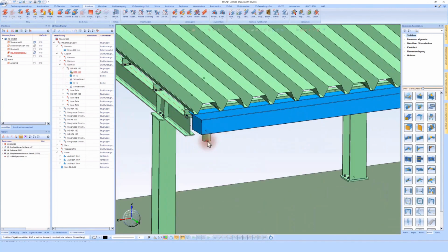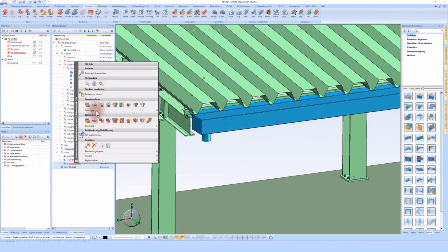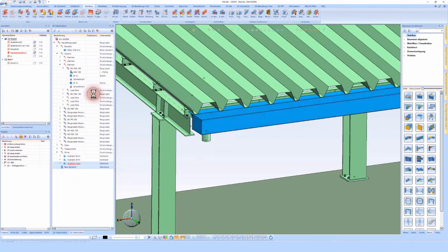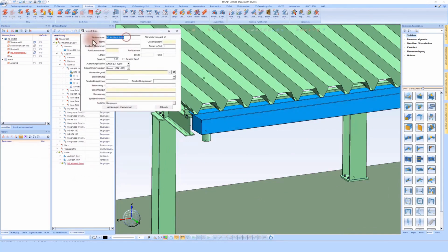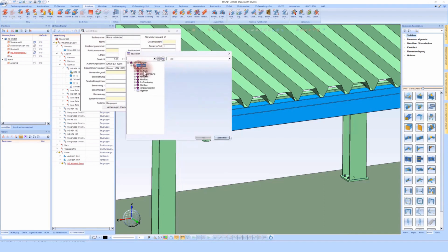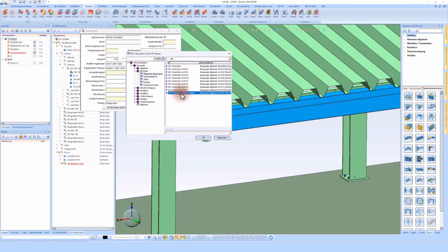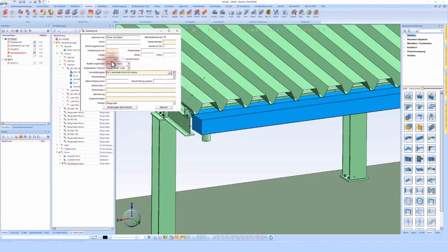In the next step, however, I would like this gutter to be welded together. That means I still need to form an assembly here. The assembly is actually to be seen as a welded assembly, gutter with drain. I give this a name, and can also define usage types here. These usage types are basically and essentially necessary for the workshop drawing. These usage types can also be independently expanded and changed from within.